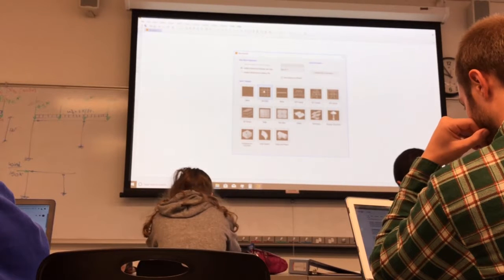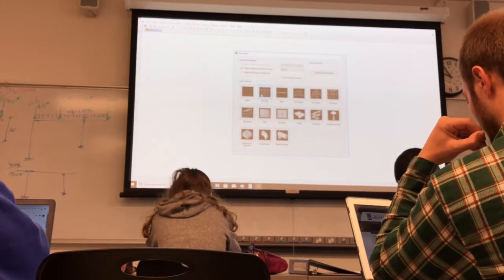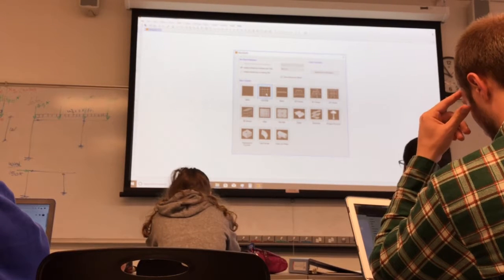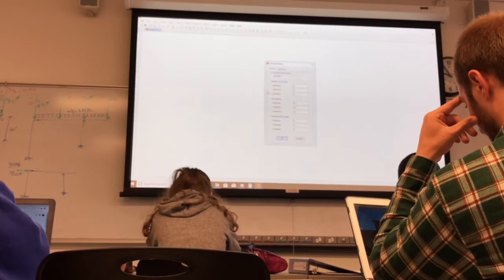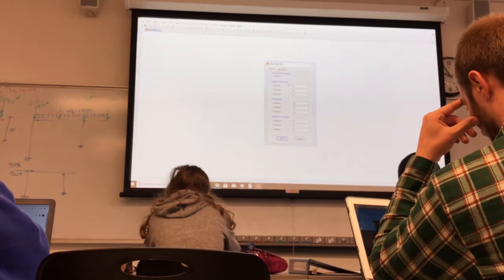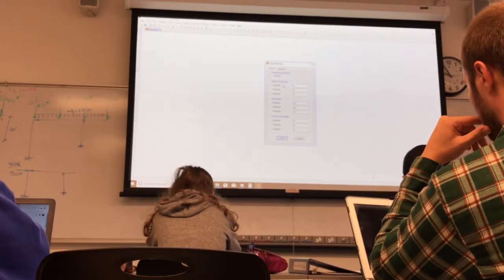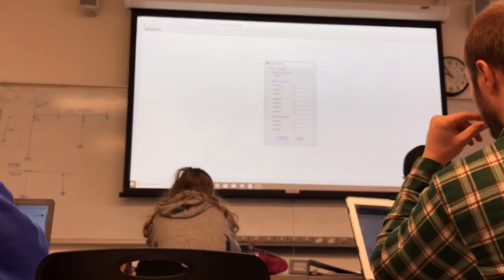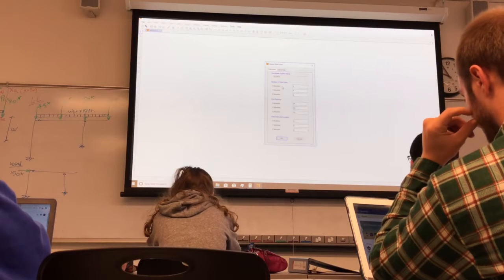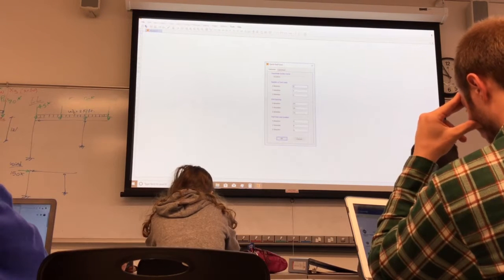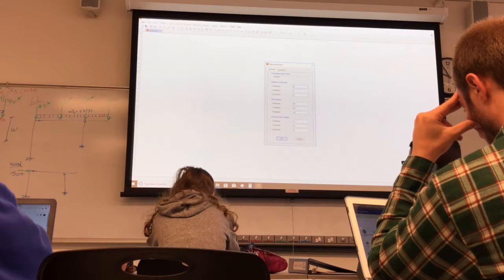And I want a grid only. That's the easiest way to do it, is to use the grid only option. So we go to grid only. If you click on grid only, it gives you the number of grid lines needed in X direction. So in X direction, I already defined that before anything. In X direction, I need only 3 grid lines. So I'm gonna put 3. Right, that's what we need, X1, X2, X3. So 3 grid lines.